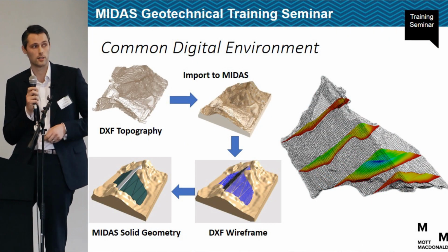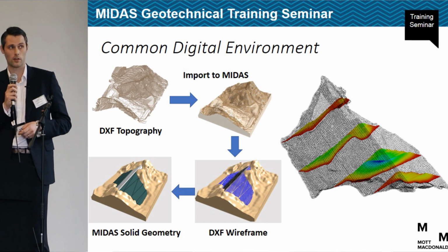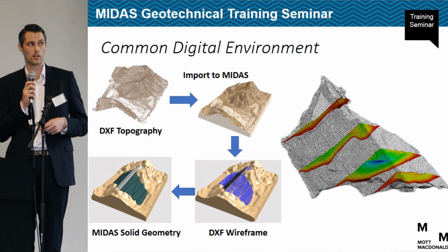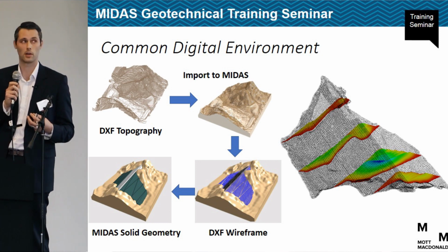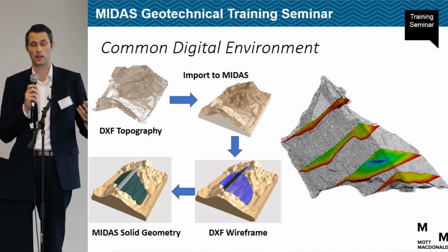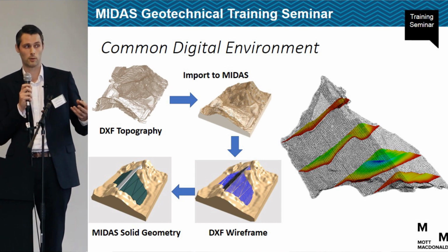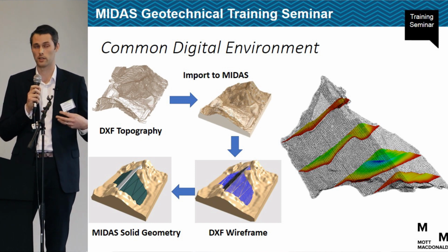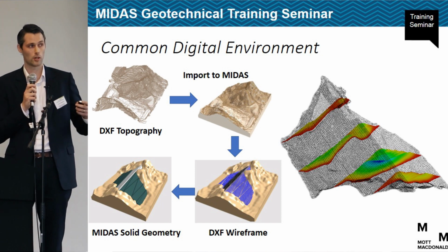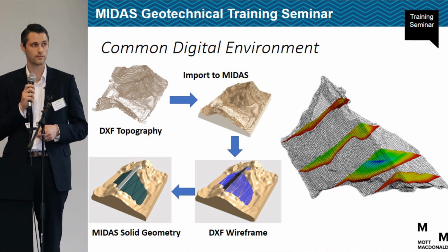Another example of that is, this was a concrete-faced rockfill dam in Colombia, where we were given the topography as a DXF by the client. We were able to import that into Midas using Terrain Geometry Maker, overlay that with a DXF wireframe of the dam, and then create our solid geometry.